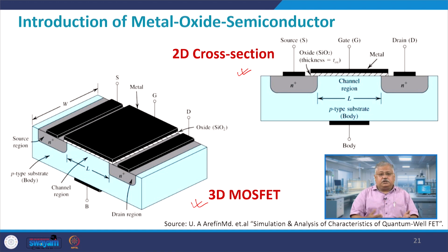Why is it known as a MOS device? Because if you look at the structure which I will just show you, it is basically a metal oxide semiconductor. If you look at the right structure here, it consists of a p type substrate. So what you do is you grow a p type substrate, which is this one, over which you grow an n plus layer. N plus is a heavily doped n type layer.